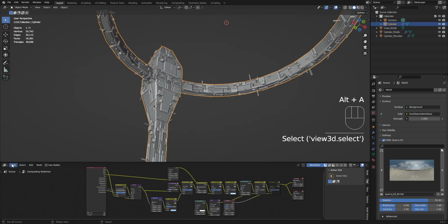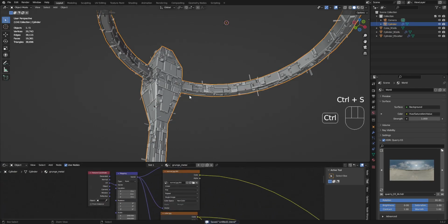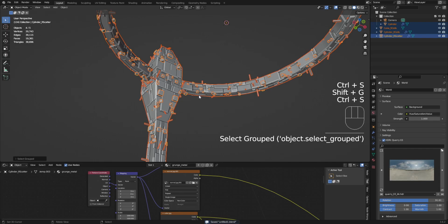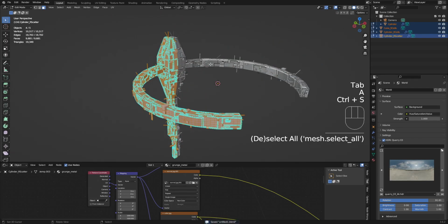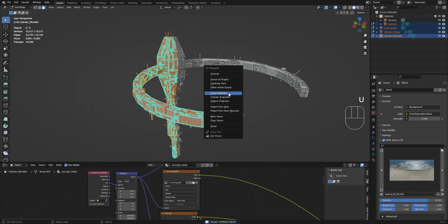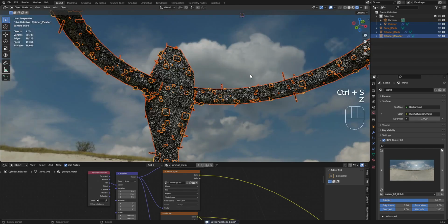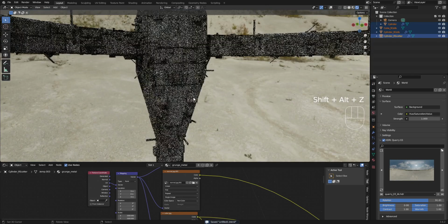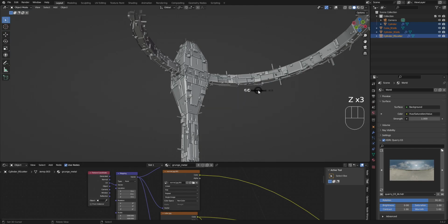And the shader is actually, I think, using a UV, and these are not UV'd, but you can quickly create a UV for this using a cube projection. Since we're just going to render this mid-range or far away, we don't need a truly specific UV for this.